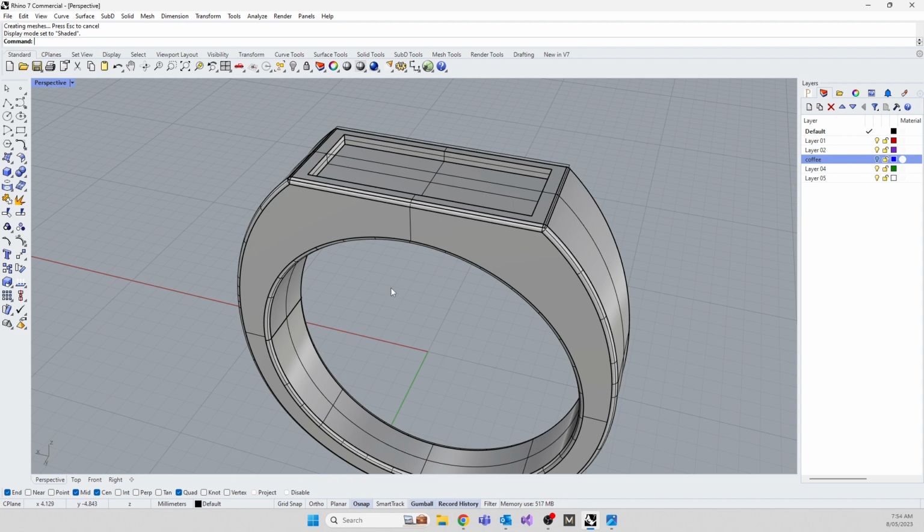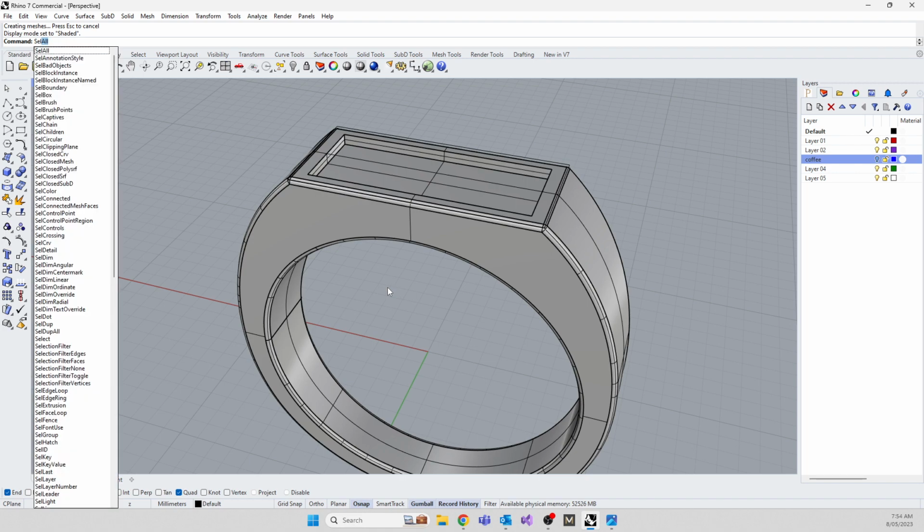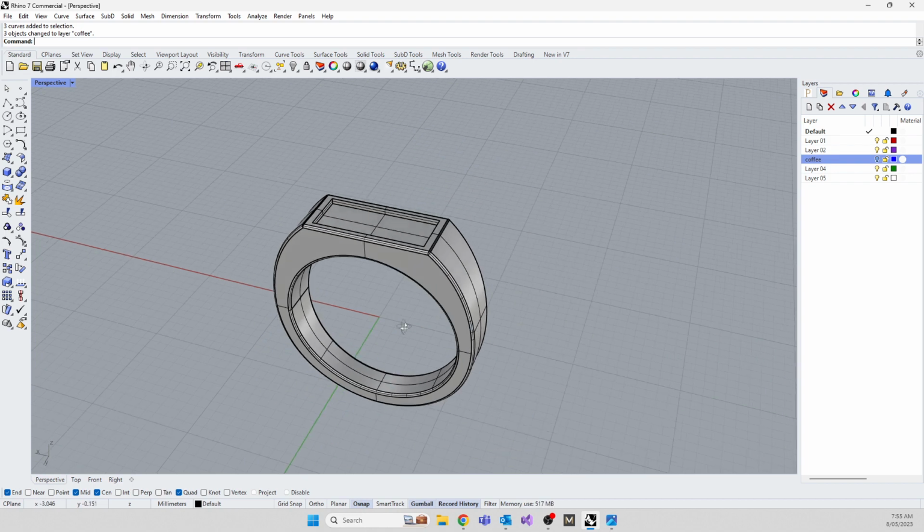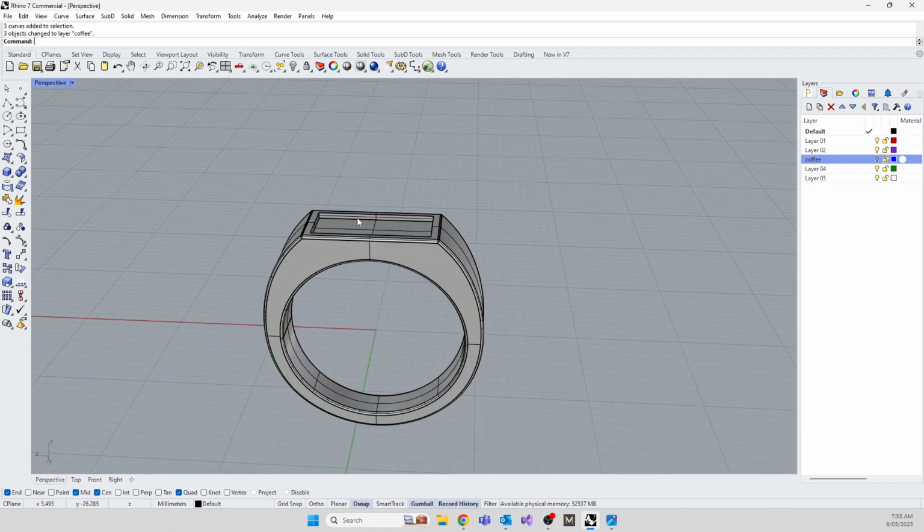So remember how dupe was all the duplications? Sel, S-E-L, is your selections. I can select all the boxes on the screen. I can select bad objects on the screen. I can select control points. In my case, I want to select all the curves. Sel curve. See what happened? It selected all the curves for me. Okay. I'm going to move them onto our curve layer, so I'm going to change the layer to here. Boop, they disappeared because the layer was turned off. So we've got all our curves together, so there's no more curves to annoy us in the screen. And we're going to start working.